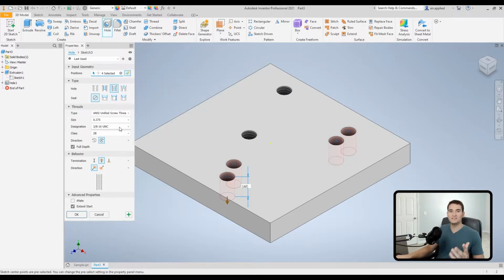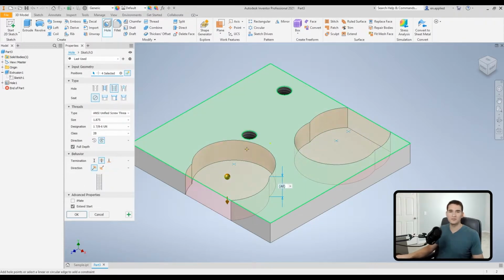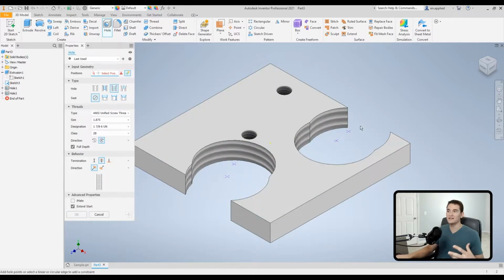Now we can pick a different feature without losing this sketch and having to go back and toggle the visibility settings in the model browser. So just remember that as you work through. So, we could change this to whatever else. It really doesn't matter. So, we could change those hole features and then do that again, and it'll keep it open and then keep that sketch visible.